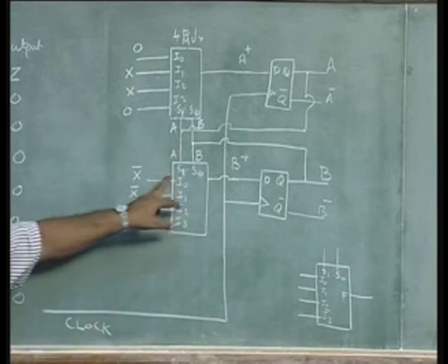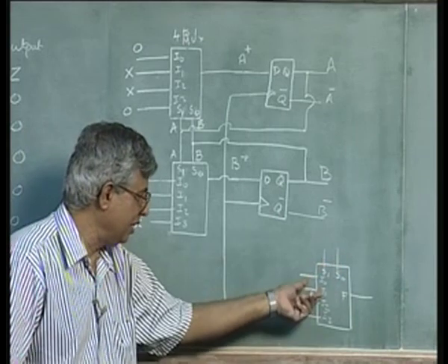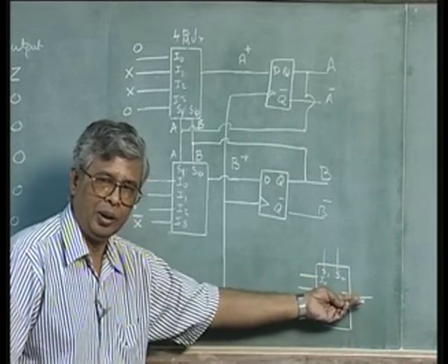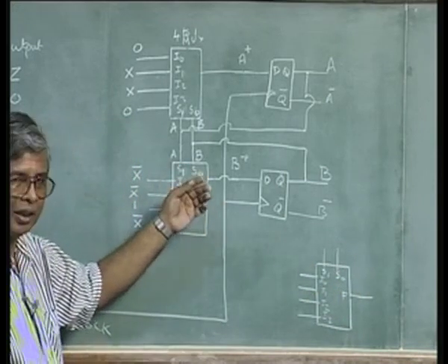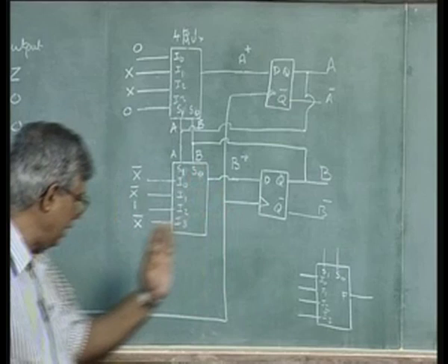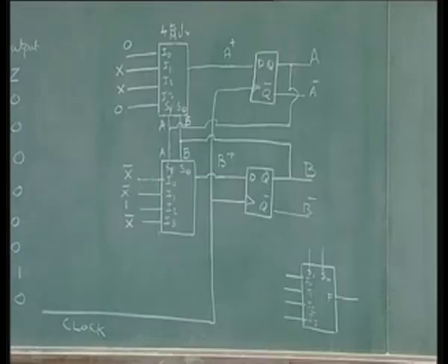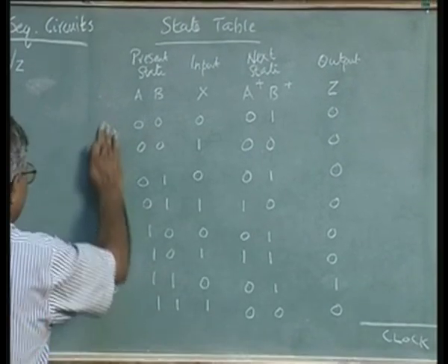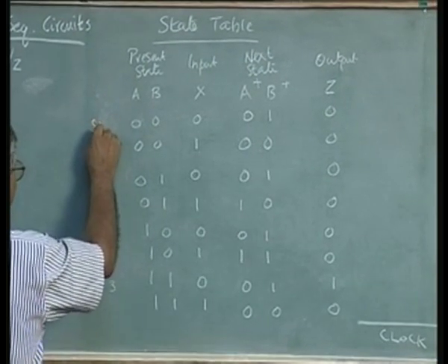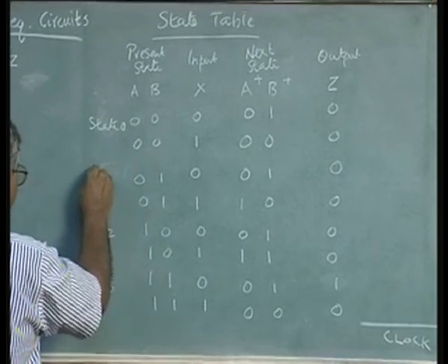That is why this S1, S0 came here, because these are selector pins, these are input pins, this is an output pin. So because of that, we got this S1, S0 interchange, but not to be confused with the S0, S1, S2, S3, because this S we are not using in the equation. This is only to indicate the condition. So if you don't like this S0, you would say state 0, so that you can completely avoid that confusion.